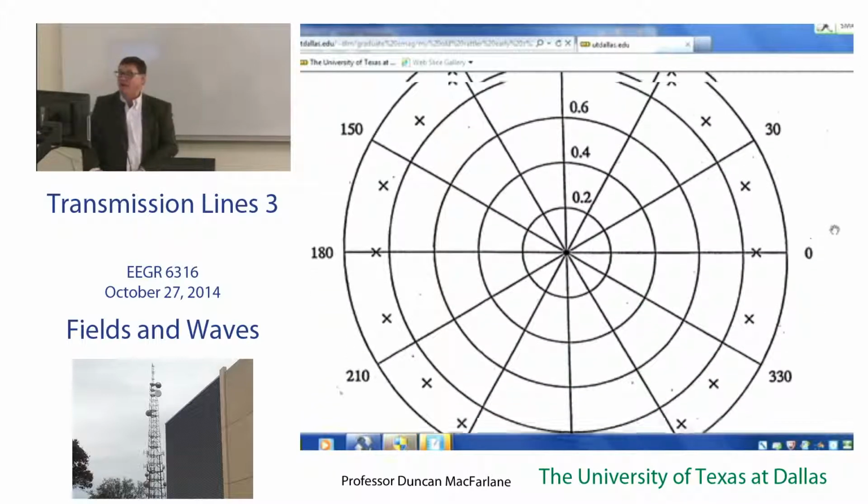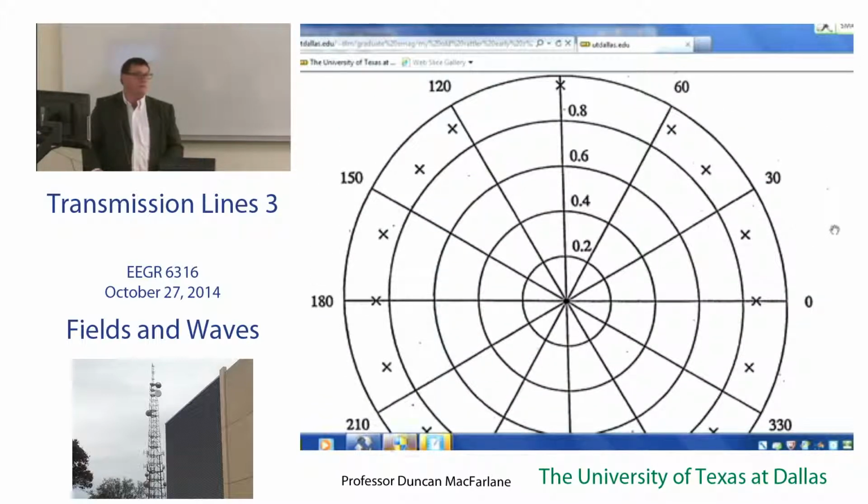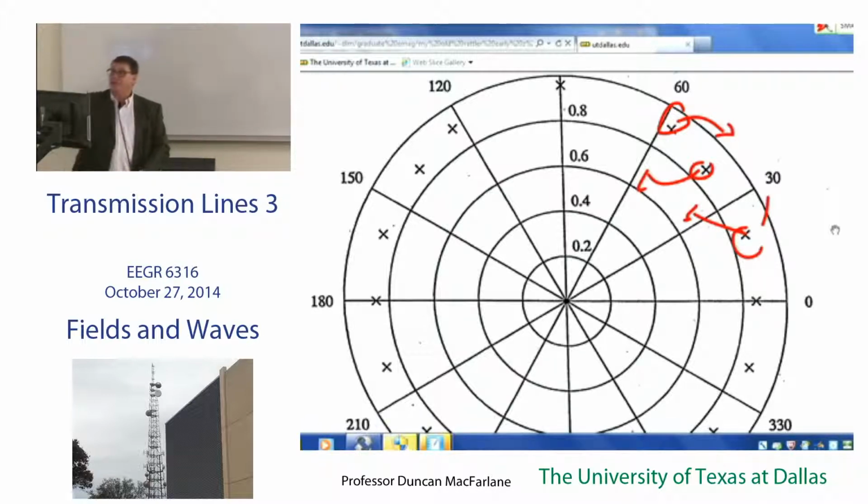Again, those of you who have taken DSP-1 will recognize this not as a Smith chart, but as a pole zero diagram. So the locations of where the poles are matter. And in fact, when you get good at this, you even start thinking in terms of moving your poles around to affect your filter response. Right?